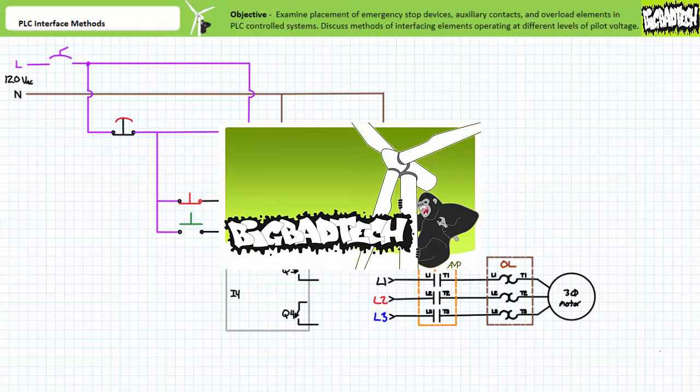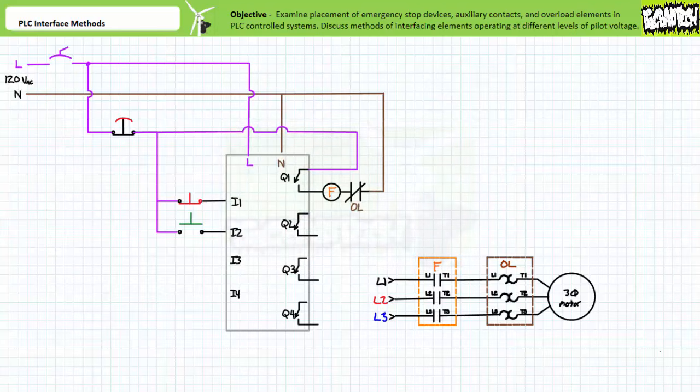The Virtual Relays and Holding Circuits for PLCs lecture, available at the Big Bad Tech channel, discusses this topic in great detail. These techniques, while extremely handy, may not be applicable for all applications due to safety concerns. The classic exception to purely virtual feedback is a motor starter, which has the very real possibility of overloading and damaging the motor if real-world feedback is neglected.